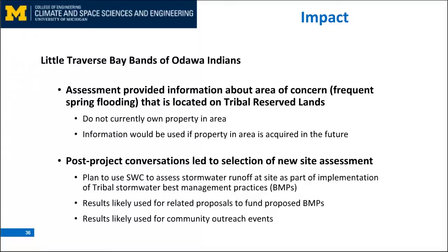After the project was done, we continued some post-project conversations, and it was indicated that they have used that information to start thinking about other sites on their reserved lands that they might want to try to do an assessment with. They're trying to develop tribal stormwater best management practices, and so certainly the Stormwater Calculator is going to allow them to do baseline assessments, as we said, vary based on season, and then also look at what the potential impact of various low-impact development controls might be.